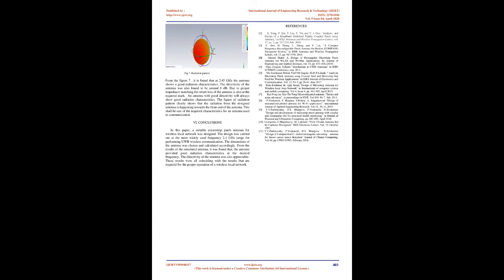The next step in design is the approximation of the length of the patch, which is given by the formula L equals. To calculate the length, the height of the substrate is chosen to be h equals 1.6 mm. V. Results and discussion. The designed patch antenna is then simulated using Computer Simulation Technology Microwave Studio. The following parameters were simulated and discussed.